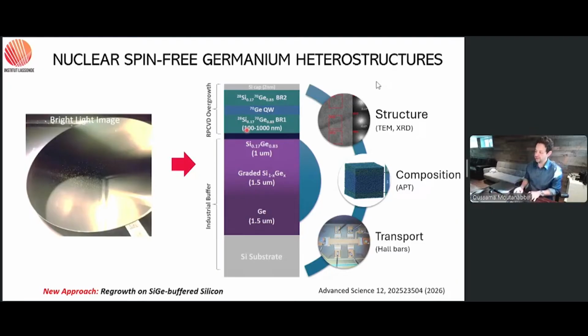It worked. But one of the challenges, as I mentioned earlier, is that starting with a silicon substrate in a CVD reactor is a much easier wafer to work with, because when cleaning silicon, you have a certain oxide that we know exactly how it behaves, and it's well established. You just anneal at high temperature, you put hydrogen, and you do all of this with chemical cleaning before.